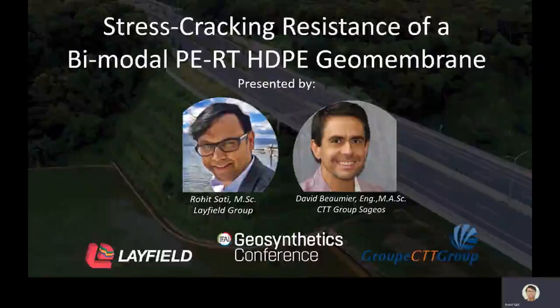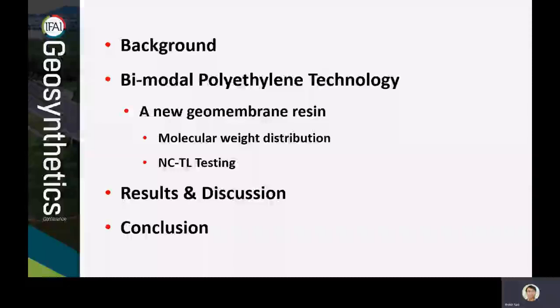Today we are going to present a study that we performed on stress cracking resistance of a bimodal polyethylene HDPE geomembrane. We also compared the material to a standard grade HDPE and to a linear low density polyethylene geomembrane, which are the most commonly used materials in the industry right now. So let's get into the presentation. We are going to cover some background information about stress crack resistance and its impact on materials.